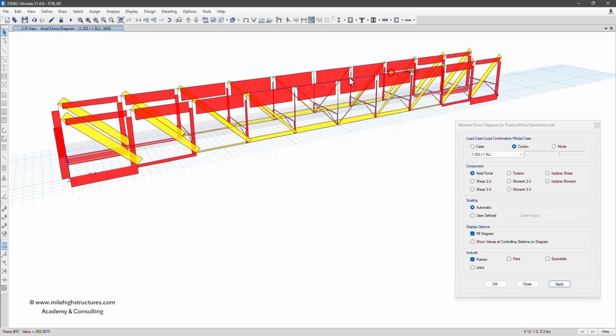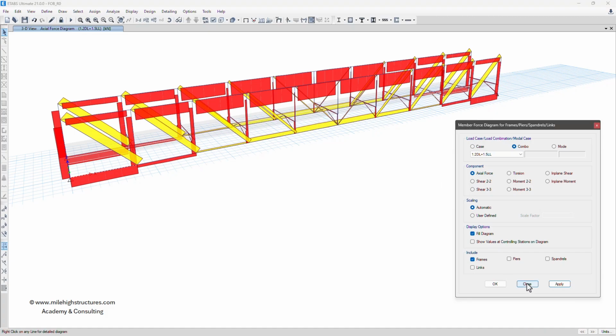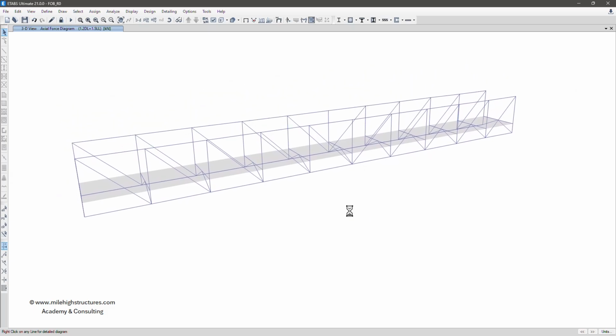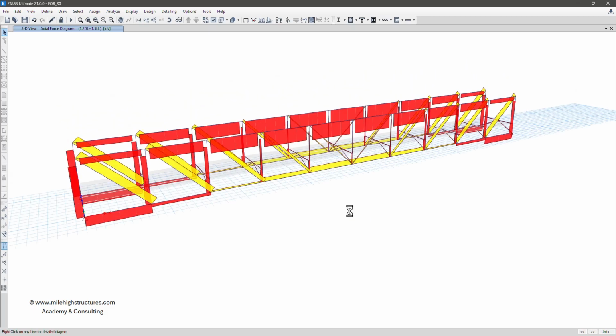Similarly, the whole top part of the truss, that is again is in, we can say, compression only, and all the bracing members, that is the ones that are diagonal and are highlighted in yellow, they are in tension. So the thing is that, we have designed it, and this is a very solid structure, and here you can see that we can decrease the size of this foot overbridge also, and we can do the further optimization also depending on the, we can say, requirement.